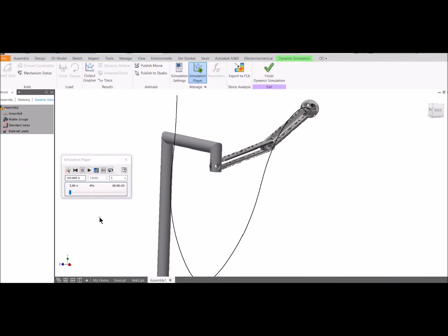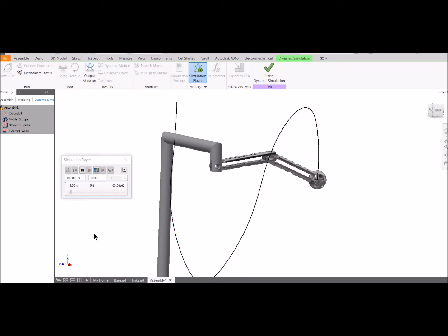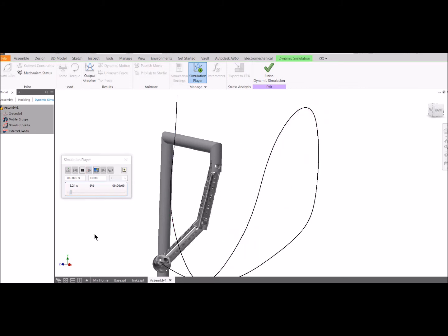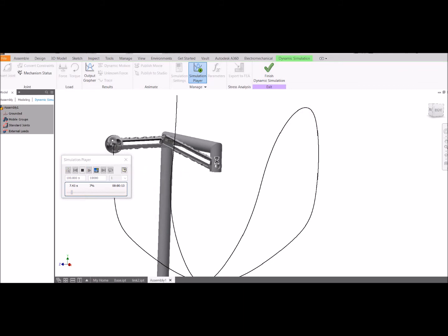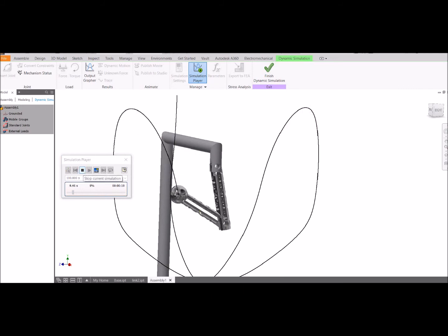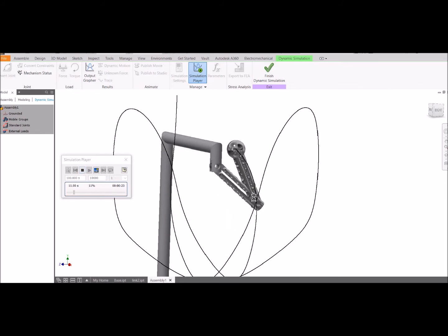Okay, for the last little bit, let's have an initial look at the joints, and we'll do a little bit more of this after we put together some engine parts. Right now, the parts are bleeding through one another. They're constrained just on the joints, but they can't see one another, and you can see they'll kind of flop through one another. So what we want to do is change this so that they're not bleeding through one another.